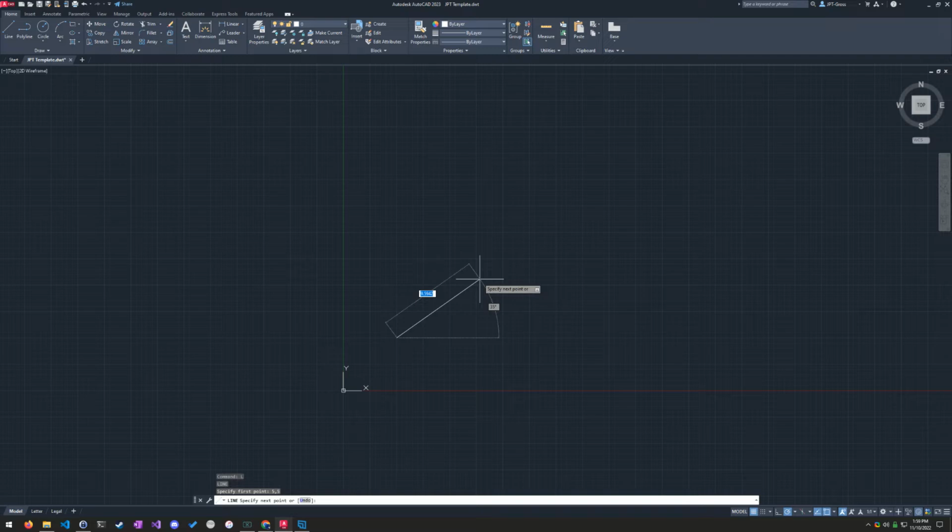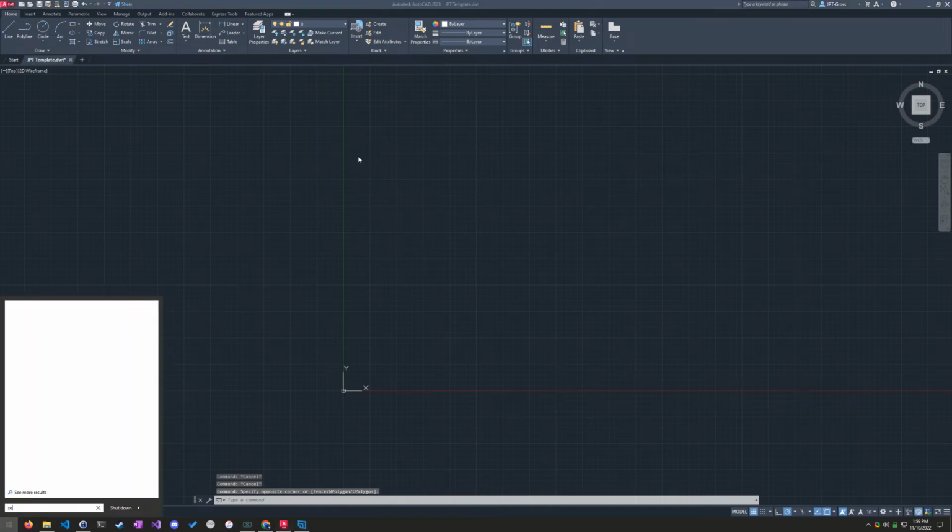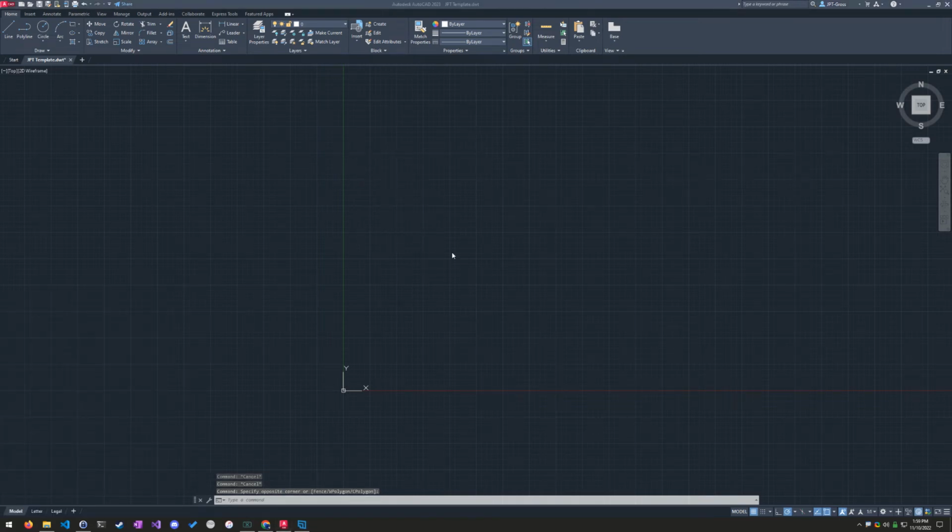And now, instead of worrying about where my mouse is pointed, I can go ahead and type in some coordinates. And there's two ways to do that, using two different symbols. If you notice where your numbers are on your keyboard, there's some symbols along with that. The exclamation point is under the number 1. The @ sign is under the number 2, and so on. So if I use the @ sign, I hold the shift key and then press 2. That's going to put the @ symbol into the box where we normally type our numbers.